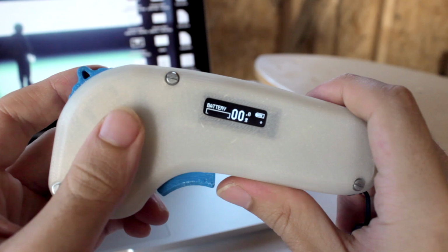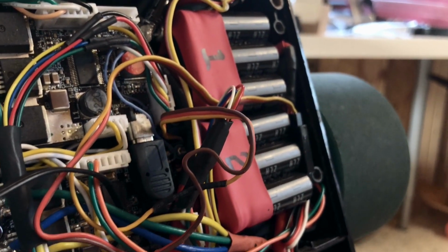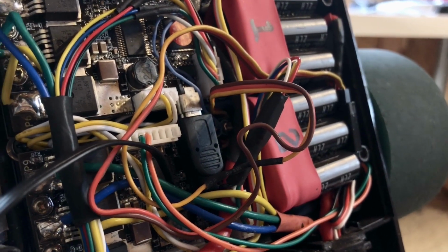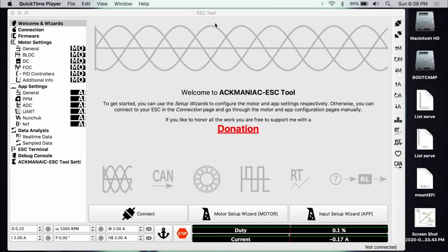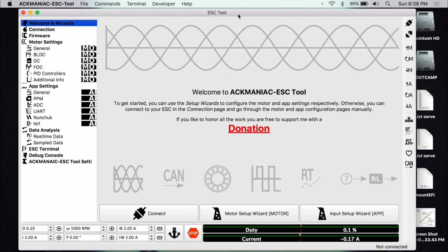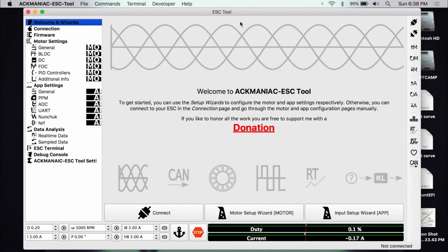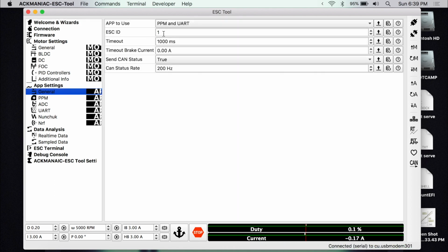Now that the remote is calibrated, let's move over to the VESC. Go ahead and power it on. Plug in your primary VESC if you're using dual VESCs like me, and open the software of choice for your firmware. You'll know if you're plugged into the primary VESC if its VESC ID is set to 0. If it's anything else, you're on the secondary VESC. Plug into the other one if you can. Or if you can't, you can press the CAN forwarder button right here in order to access the primary VESC from the secondary VESC's USB port.